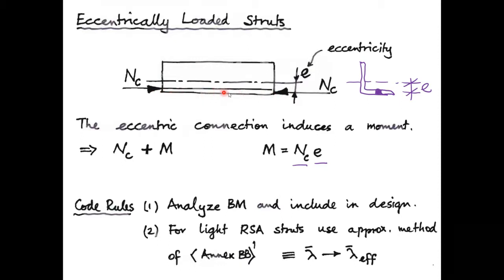to one leg, but the centroidal section is somewhat a distance e, an eccentricity, away from the load that's been applied. And we know that if we have an eccentricity and a load times the distance, or the lever arm, that will give us a moment. So therefore, as well as having an axial load along the length of this member, we also have a moment at the end of it. And that moment is induced because the load is applied at an eccentricity away from the centroidal section. That moment is the axial compression load multiplied by the eccentricity.